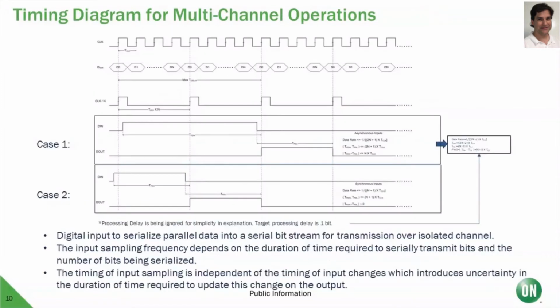One thing that's unique, though, about our ceramic digital isolator is the fact that we multiplex the data across the capacitors when we have multiple channels communicating in one direction. This is because the capacitors are large, so we don't have the space inside the package to dedicate a capacitor for each channel of data.